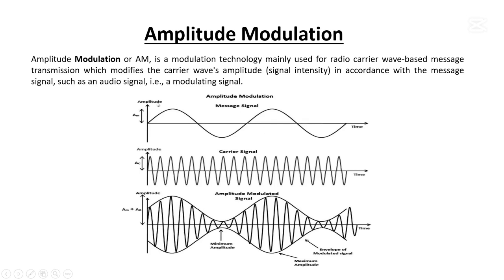So here this one is our message signal. You can see 1 kilohertz of a sinusoidal wave. And the other thing we have is the carrier wave. What actually happens here is that we have to convert this low frequency message signal, which is 1 kilohertz, into a high frequency signal with some modifications so that it can travel far enough and we can deliver our message far away.